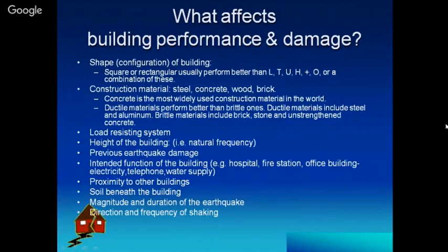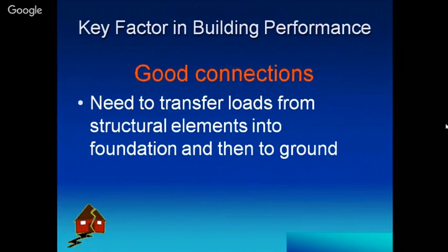Soil beneath the buildings means you are supposed to take care of the geotechnical part of the building. Soil investigation should be there, and it should be proper. Whatever parameters are going to be considered should be there. Magnitude and duration, direction and frequency of shaking. Key factors in building performance: good connections. That is for both cases, but it is more critical in the case of masonry, because reinforced cement concrete is in itself a homogeneous type of material used in construction.